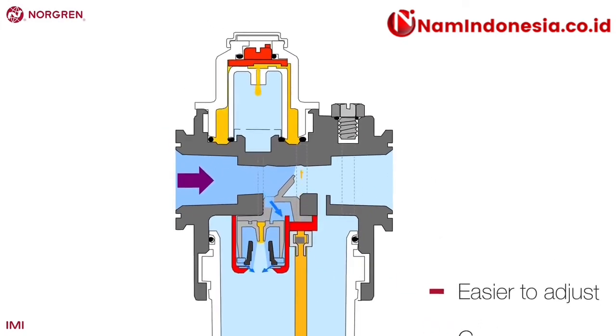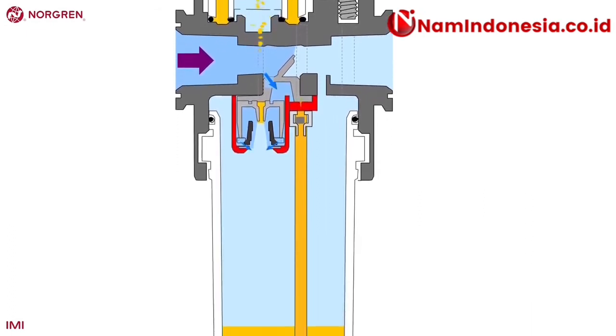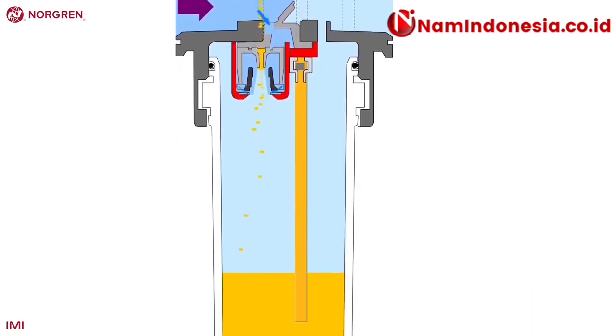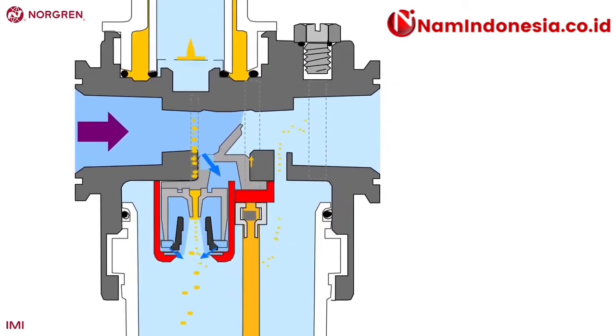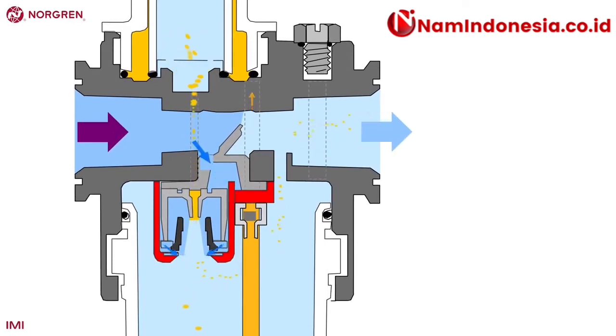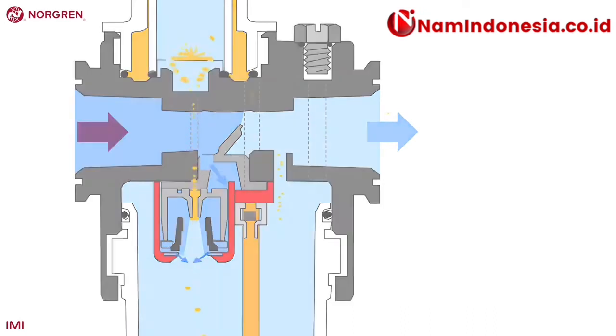This time, most of the oil that has dripped down from the sight dome goes back into the reservoir. It's only the smallest 10% of particles that get caught in the Venturi effect, sucking them into the outflowing air and downstream. As with a traditional lubricator, a minimum flow rate needs to be achieved to begin the process.